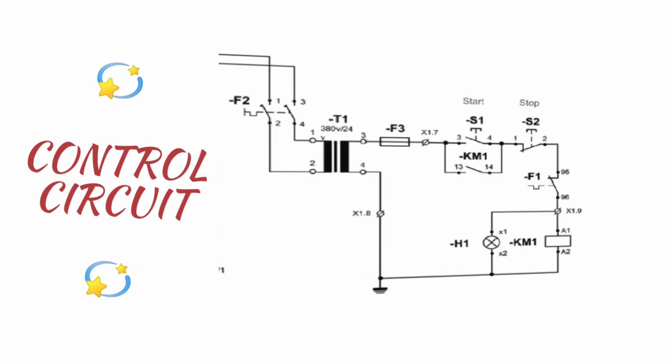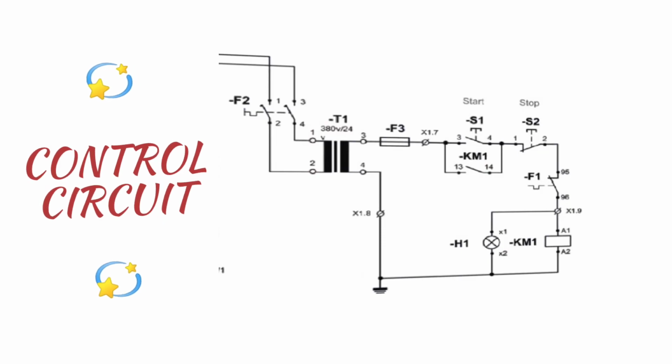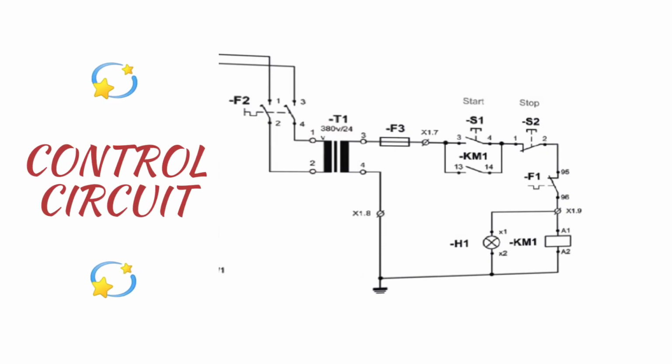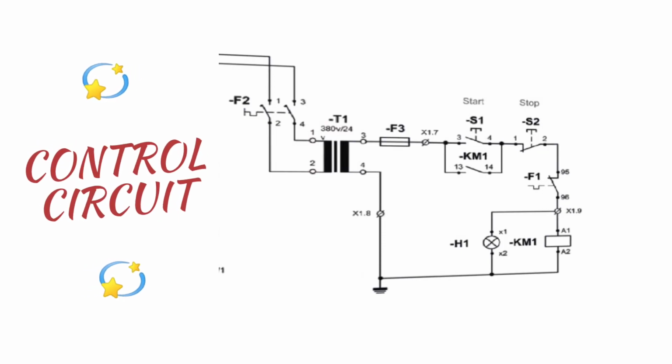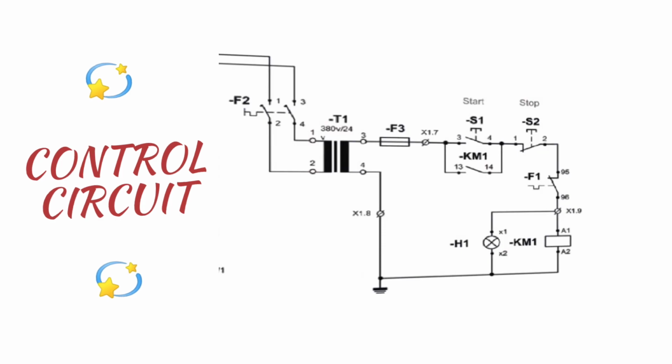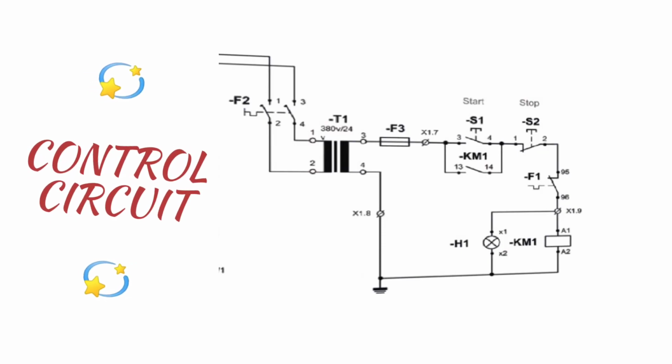Overload relays cut off current to the motor when a high current situation develops due to ground fault, short circuit, phase failure, or mechanical jamming. To start the motor again in such a case, F1 should be reset by hand after the internal heater's cooling down time.